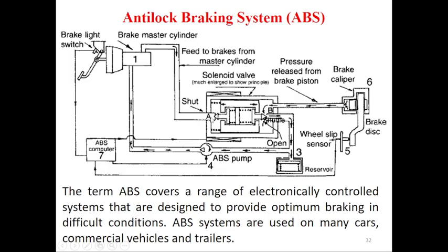From point A, force is applied and the oil moves to point B with the help of a piston, which acts with the help of a solenoid valve. This solenoid valve connects again with the reservoir. This reservoir supplies the ABS pump, which supplies the anti-lock braking system computer.